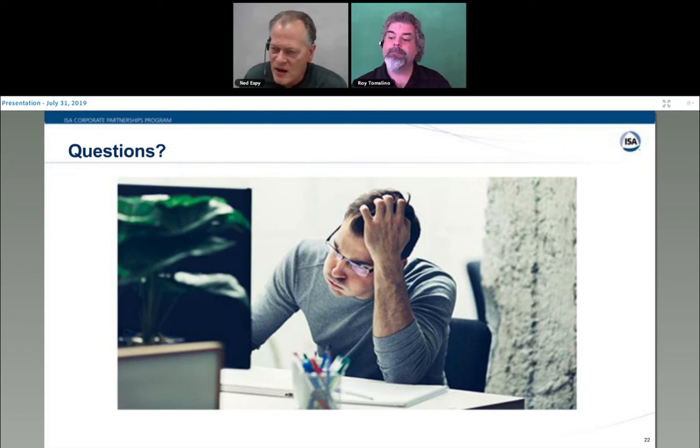So here's a scenario from Justin. Your RTD is drifting positive 2%, but the DCS at the same time is drifting negative 2%. So then the indication is spot on during the closed loop cal. And so Justin wants to know, am I not worried about drifting of these two elements?